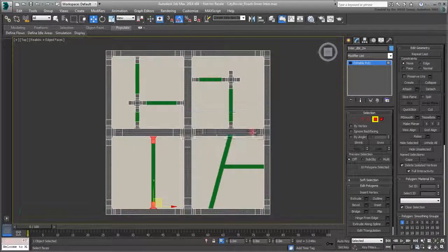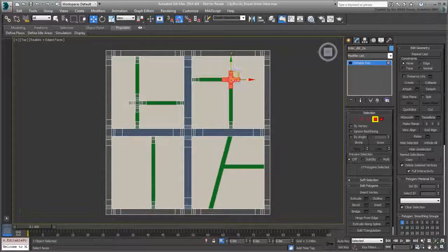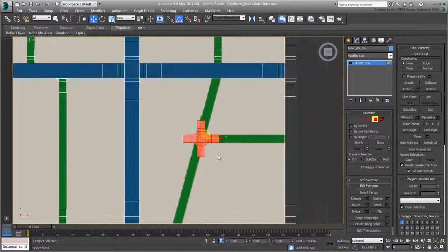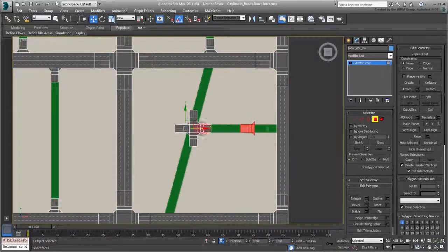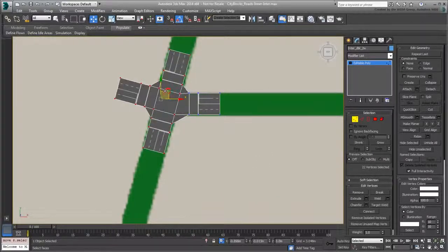If you have angled roads, as you do here in the bottom right corner, start by setting up the main intersection by copying it from another element. Before you start reshaping it, you may want to extract the T-junction to the right. You may be tempted to rotate some vertices, but the truth is the road markings should be more aligned with the intersection.